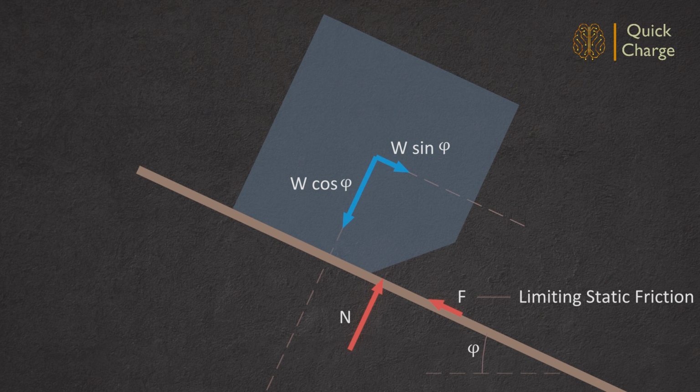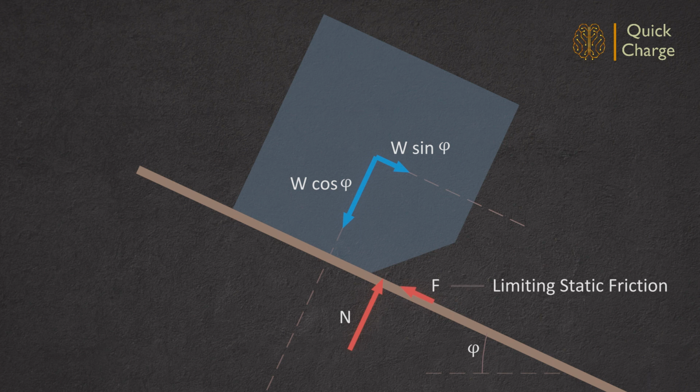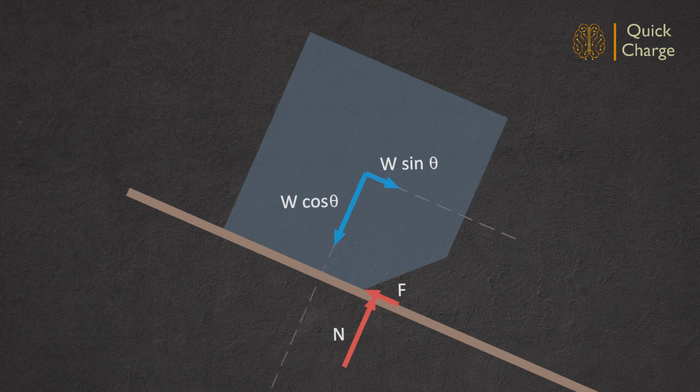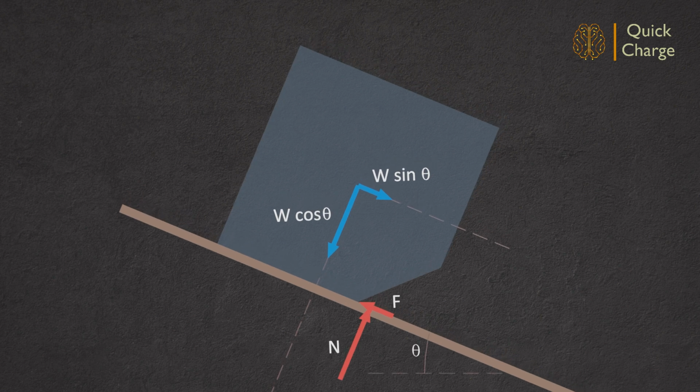As the frictional force is independent of area of contact, the same frictional reaction will be developed and force equilibrium is maintained in that parallel direction. However, the line of action of the normal reaction cannot be outside the box. In order to correct this, the parallel component of the self-weight needs to be reduced. This is achieved with a reduced slope of the inclined plane. With this, the parallel component as well as the frictional reaction is reduced such that the normal reaction is moved back to the edge.